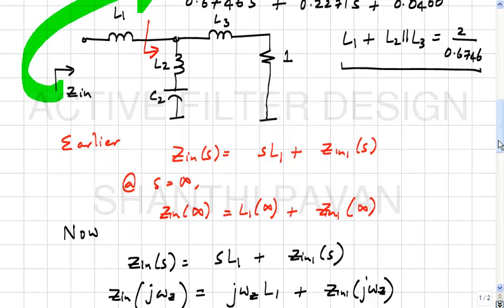If you think about it, it is pretty much the same thing that we do with the all pole ladder synthesis, right. When there were only poles in the transfer function, for example, in the Butterworth and the odd order Chebyshev case, we found that the network simply becomes an LC ladder, and at each step of the way, what we were doing was letting s tend to infinity and equating the coefficient of either the impedance or the admittance to the inductance or capacitance.